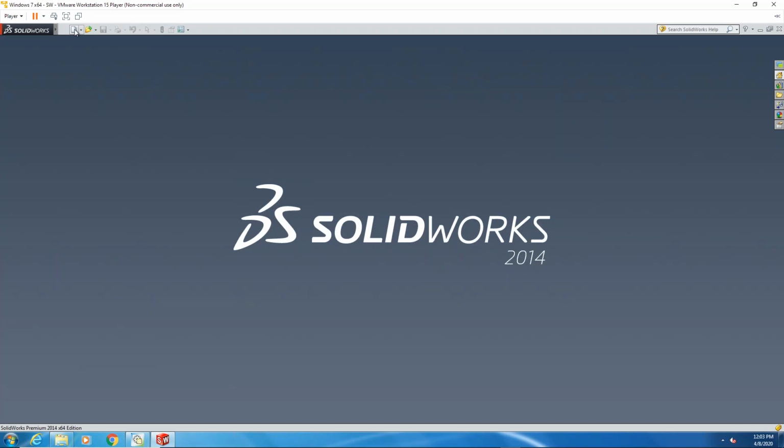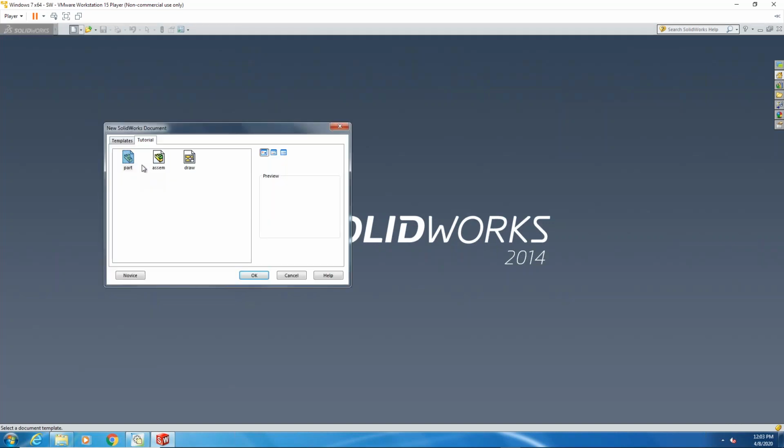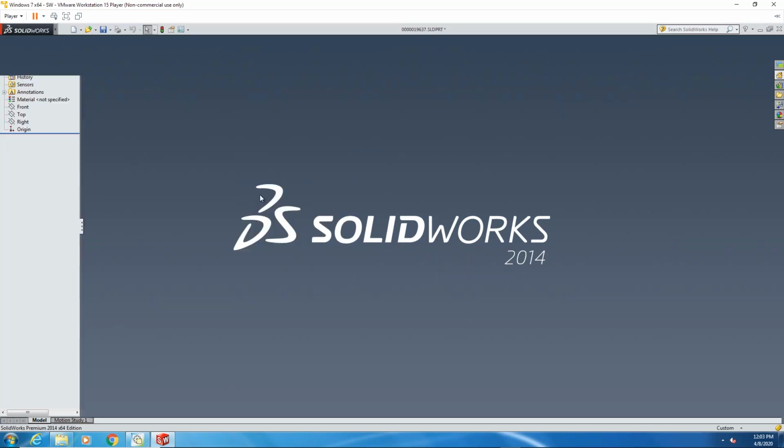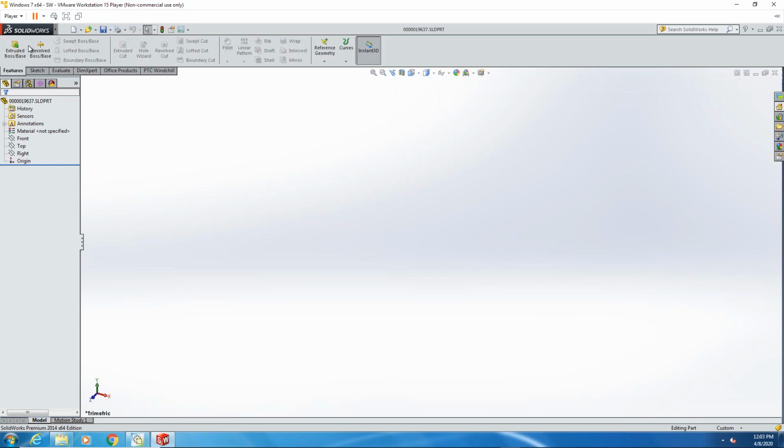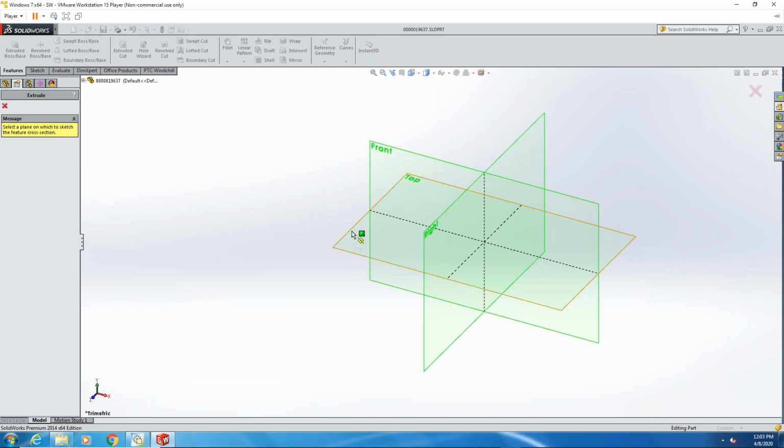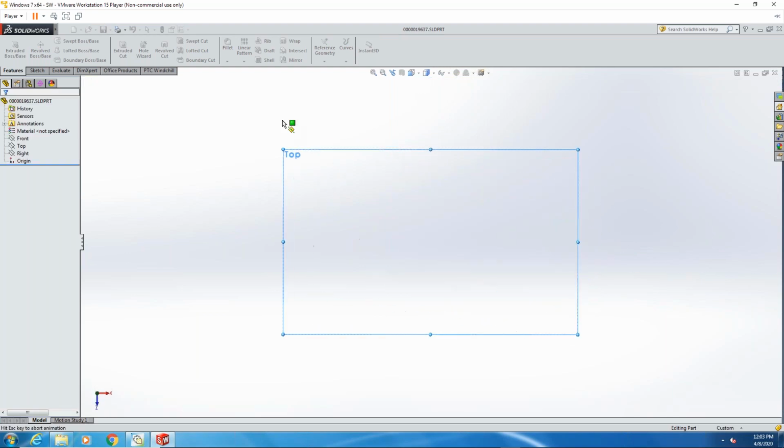All right, so now I'm going to go ahead and create a brand new file. This is going to be a part. I'm going to go ahead and say, okay. Now, mind you, as you saw in my information, I've been using PTC products for a long time. So learning some of the SolidWorks things was a little bit interesting for me, but I'm gonna go ahead and create this feature, extruded boss, and start it on there.